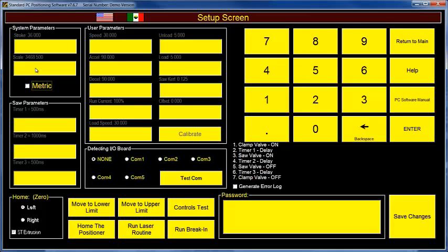If short parts are perfect, and long parts are off, and anything in between is progressively worse towards the worst case in the longest part, then it's a scale factor problem. That is addressed in step 2 of the calibration routine, but you normally won't have to change it.